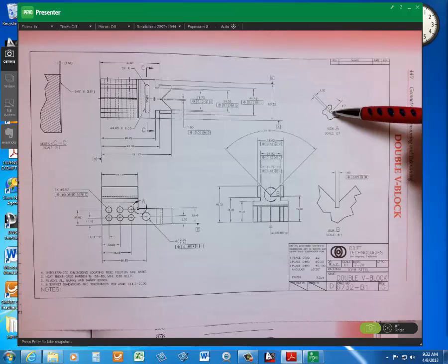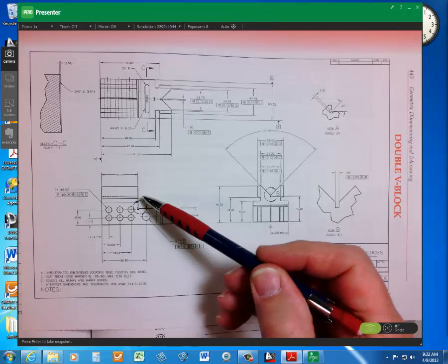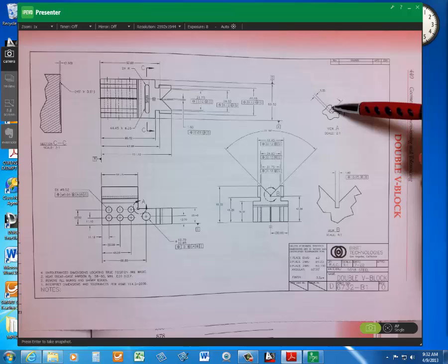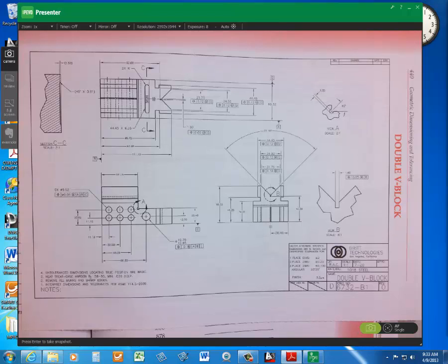Well, if you have to fit a square piece up in there, it allows relief for the corner of the part that might fit up in there. And you also quadruple the strength of that corner because you added surface area that wasn't there. Instead of coming to a sharp corner, now it's rounded and you have that much more surface area.